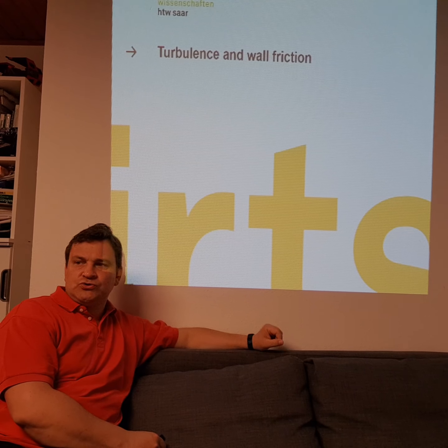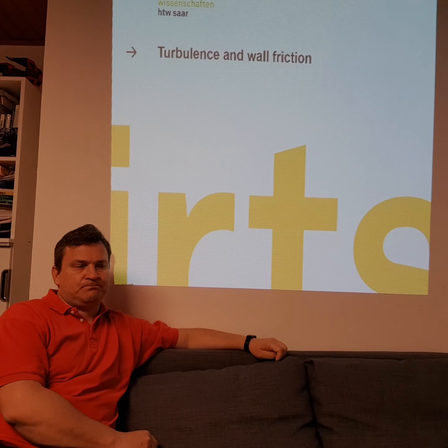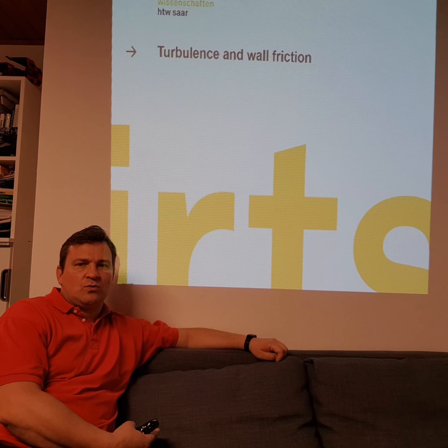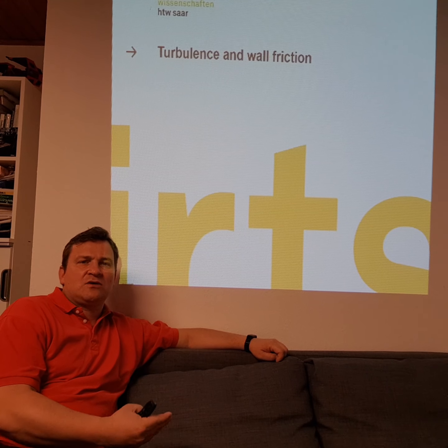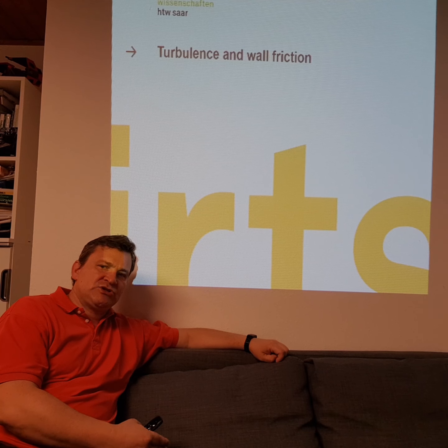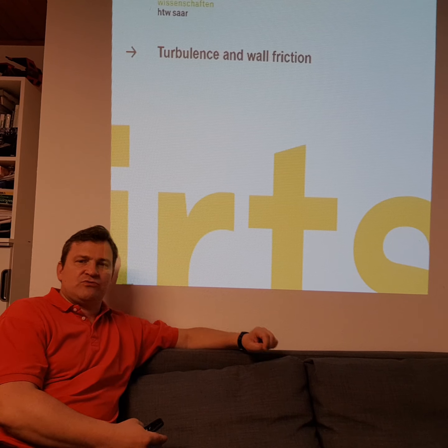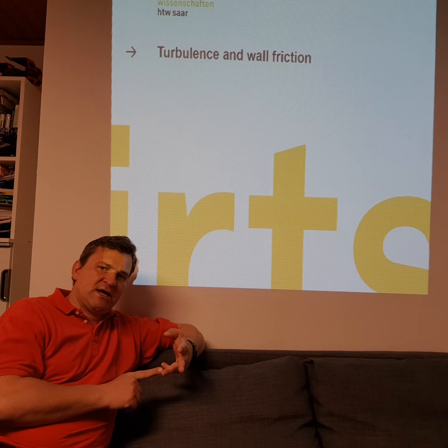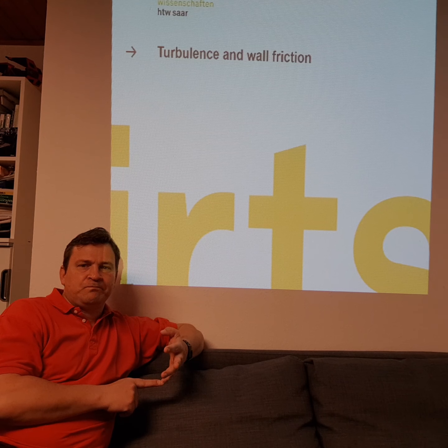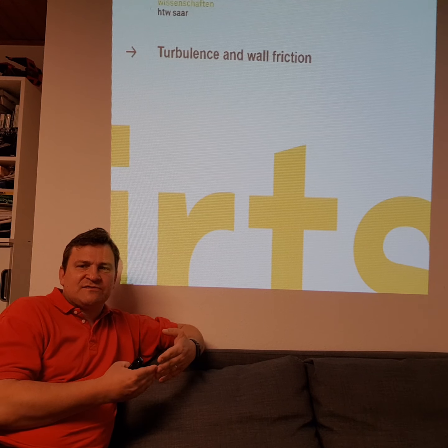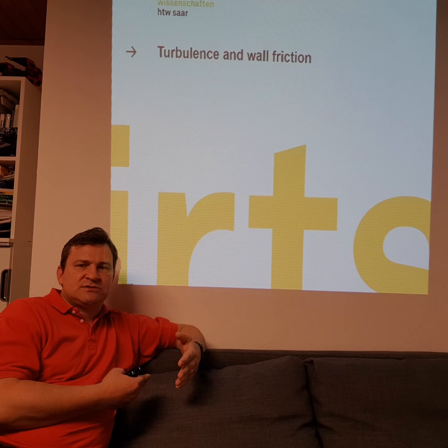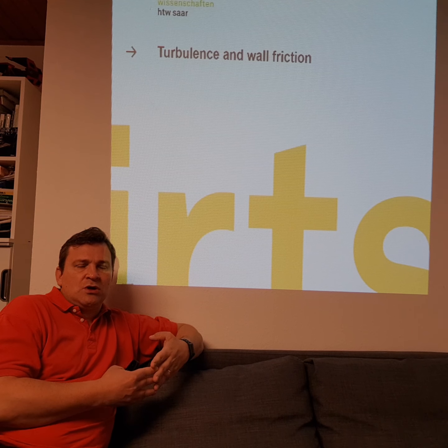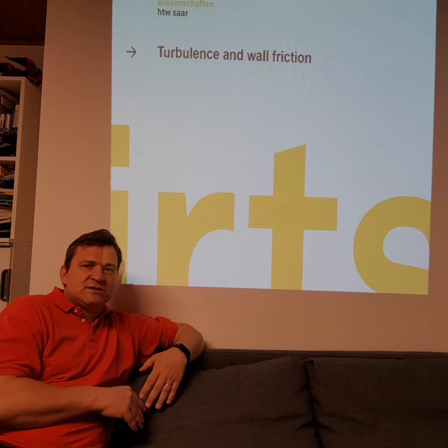Let's have a look at turbulence and wall friction. I already introduced what turbulence is, what the Reynolds number is, and how we can calculate if a flow is turbulent. The Reynolds number is density times velocity times characteristic length divided by viscosity. So if we have fast flows, we get high Reynolds numbers, and that means we get turbulent flow.